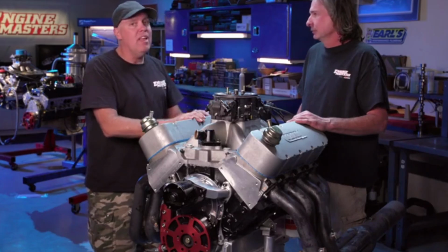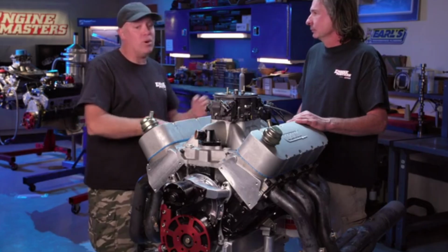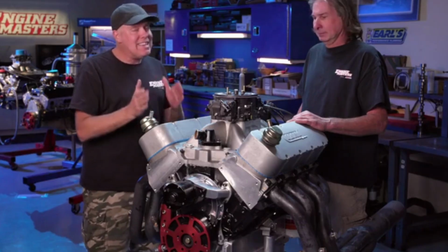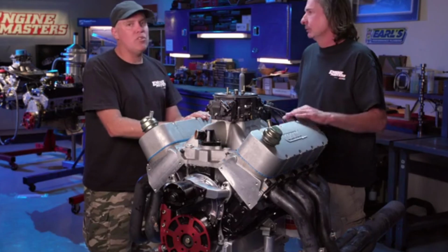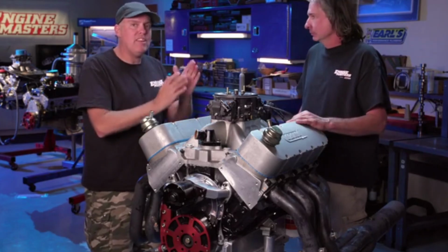Right. One guy I trust a lot, David Rayer from Rayer Morrison Racing Engines. This guy is top end, very respected engine builder. And his opinion, after a huge test that they did on a NASCAR engine with a really short rod and a really long one, and what he said was hundreds of camshafts, was exactly the same thing, 0. So I did let that influence this a little bit, but what really impressed me is when we did the static test at 3,000 RPM and 5,700 RPM, we found out at that point, we had identical results. Identical results. And so that kind of takes everything but the rod length itself out of the picture. There's no inertia problem and there is no ring flutter problem. Yeah, we're eliminating variables and we're just basically getting down to distilling the facts.